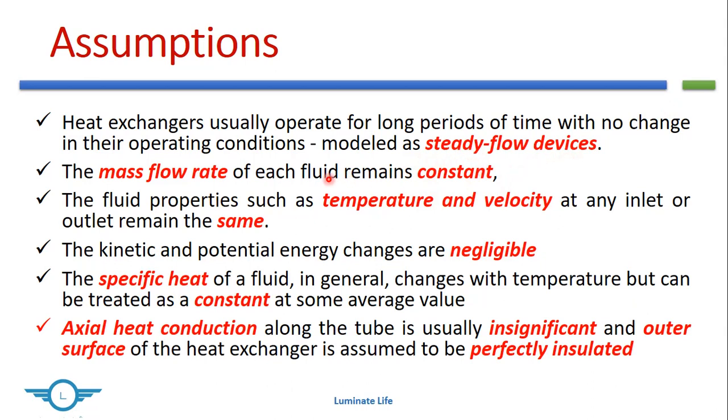Second, we assume that the mass flow rate of the fluid elements remains constant, that is, the hot fluid as well as the cold fluid will have a mass flow rate which remains constant. Properties such as temperature and velocity at inlet and outlet tend to remain the same. Kinetic and potential energy change is negligible.